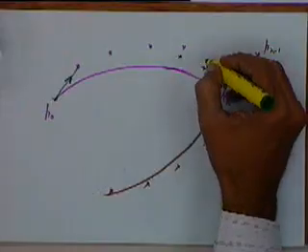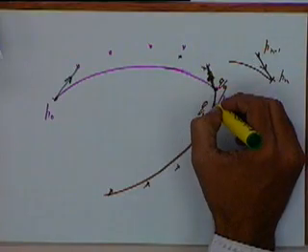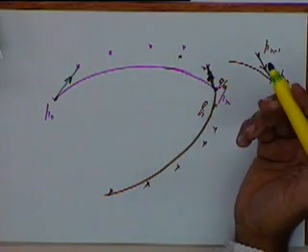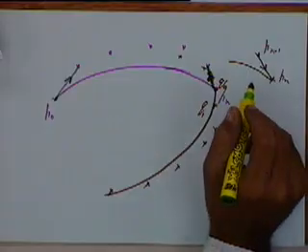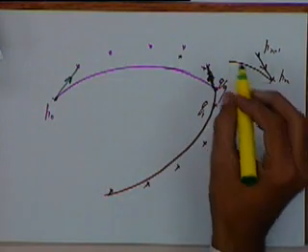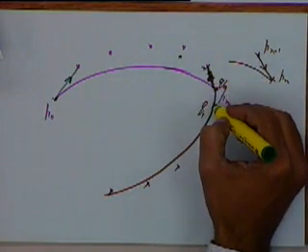Okay, you are saying something? Like in a composite curve, we ensure C1 continuity by fixing the Pn minus 1 and Q1 points. Yes, we will ensure the C1 continuity here by fixing these 2 points. If they are collinear, that's C1 continuity. So that's a simple way of ensuring C1 continuity.